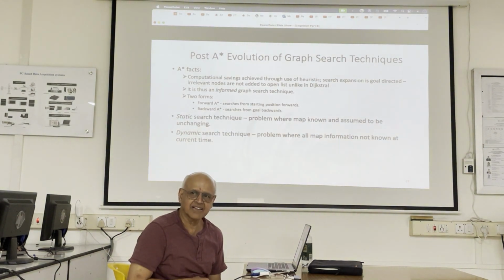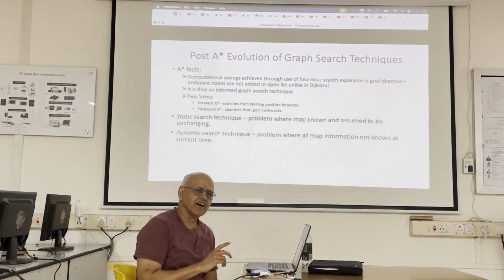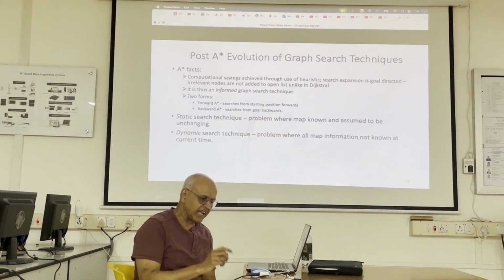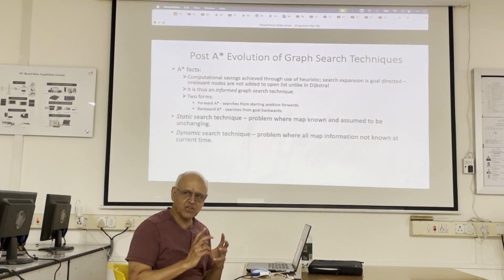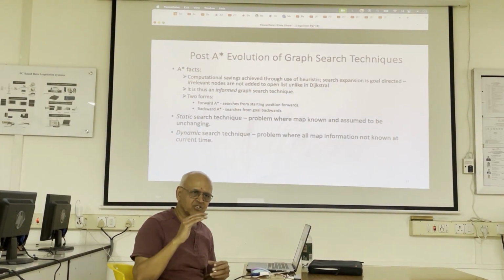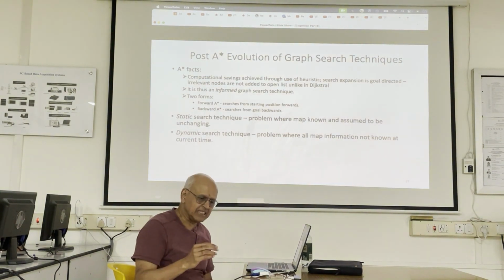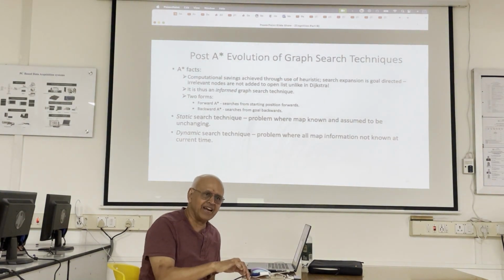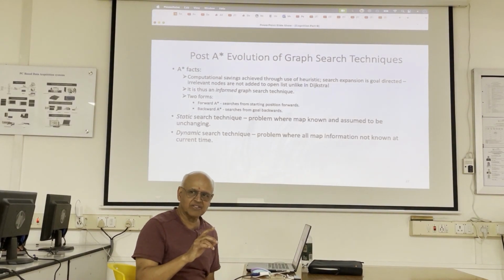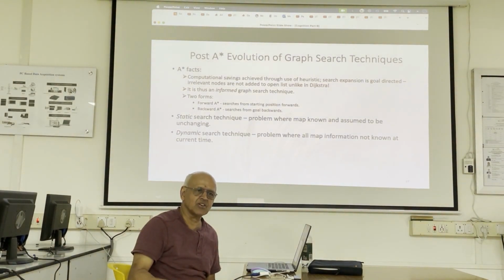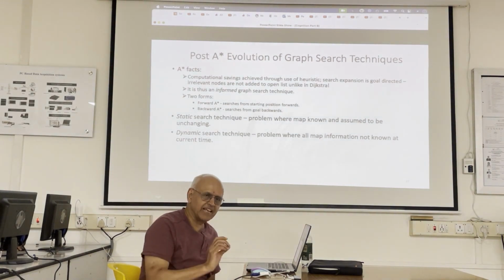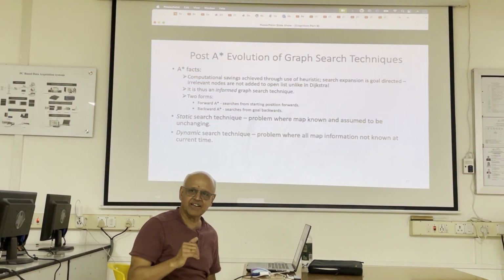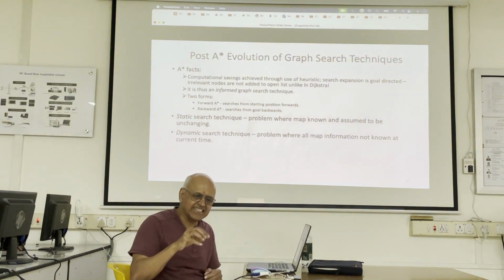Yeah, right. And so there was a group that came up with an algorithm called D star light. They figured out that you can save the cell values. You don't have to shut down the program, but when you see an obstacle, certain values need to be repaired. And they found out that the whole environment does not need to change. You don't need to repair the cell values everywhere. They came up with an algorithm where if they spot an obstacle in a place where they thought there was nothing, they can just repair a few cells.